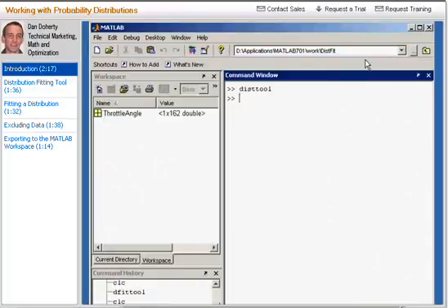The second GUI we'll introduce generates random samples from any of the 20 available probability distributions and displays the samples as histograms. It also lets you export the random samples to the workspace, which you can use to test hypotheses or models under different conditions. To open this GUI, type randtool at the MATLAB command prompt.